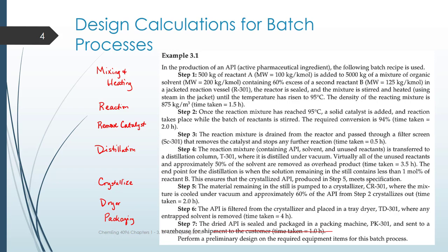Next, we need to crystallize our product. The material that remains in the still is going to be pumped to a crystallizer where the mixture will be cooled under vacuum again, and about 60% of the API from step 2 will crystallize out. This should take 2 hours.